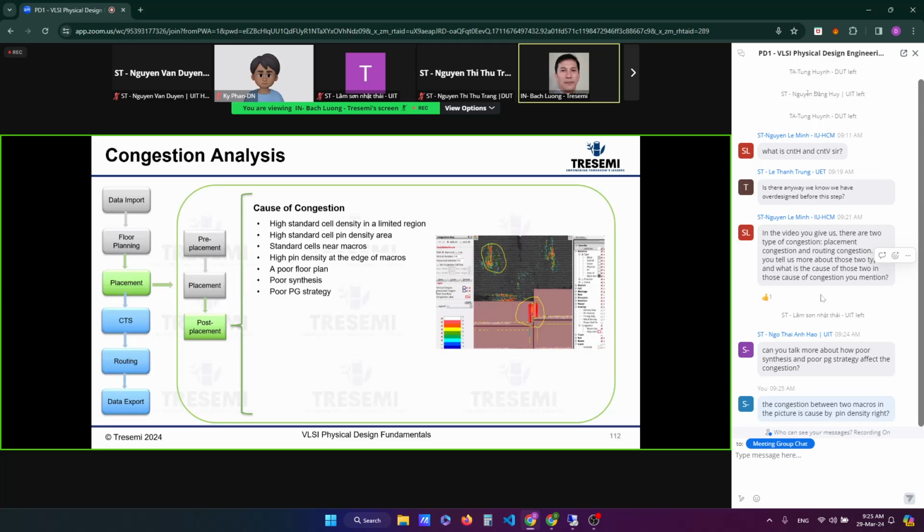Based on that, it will do buffering and so on. It will add buffers and things like that to try to meet the timing, but based on the wire load models. So let's say that target is hit, so you met timing in synthesis. But when you go to placement and time it after you place, you can see there's a huge gap.